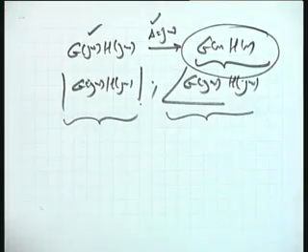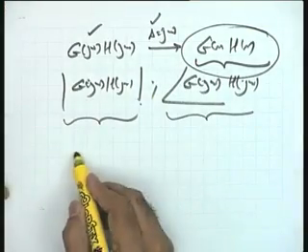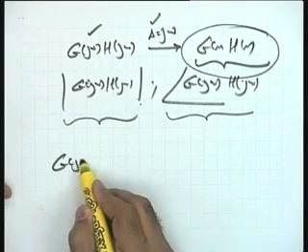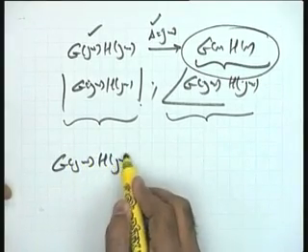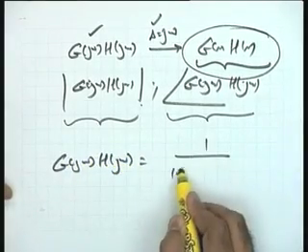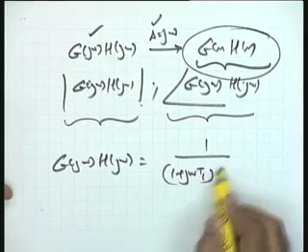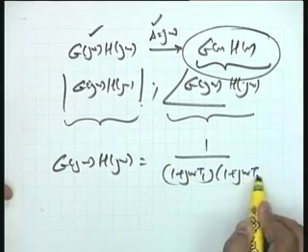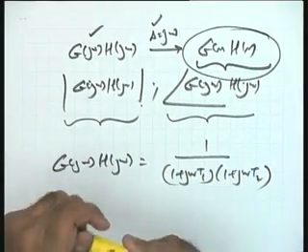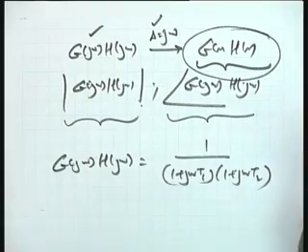Okay. Coming back to the original problem, the open loop system is given by a transfer function whose sinusoidal form is 1 over (1 plus j omega t1) into (1 plus j omega t2). I am interested in a rough sketch. I am really not interested in the total quantitative plot. If the total plot is needed, probably the power of the Nyquist stability criterion is lost. I am interested only in the encirclements of the -1 point.